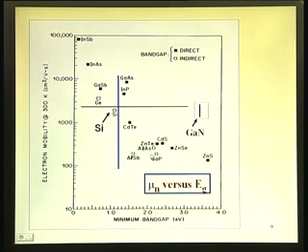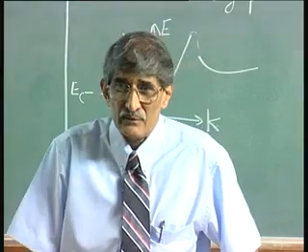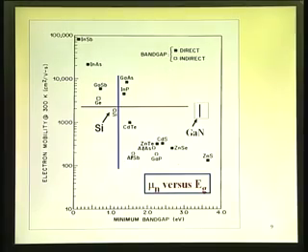Here you can see the band gap of gallium nitride, GaN, is something like 3.49 electron volts, and you can imagine what the intrinsic carrier concentration will be. When you went from silicon, 1.1 electron volts, to gallium arsenide, 1.43 electron volts, the intrinsic carrier concentration fell from 10 to the power 10 to 10 to the power 6, almost 3 to 4 orders of magnitude down. If I go to gallium nitride, which is 3.5, there are practically no electrons.